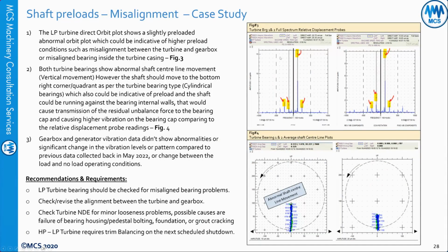And this one here was the proximity probe readings. As you can see, 1x and 2x; in the forward precession 1x was higher amplitude, but 2x was smaller, and the dominant vibration was at 1x, but in microns it was very low.